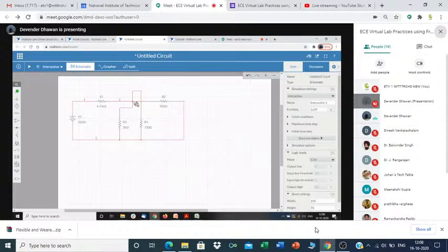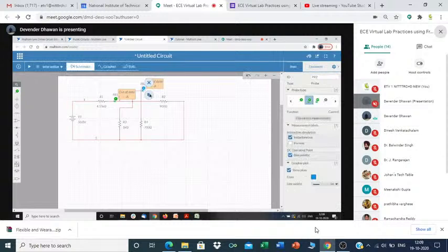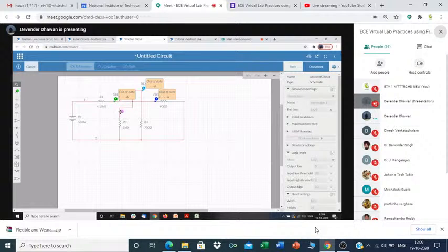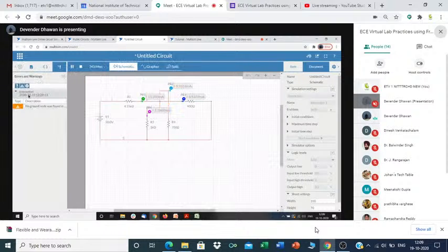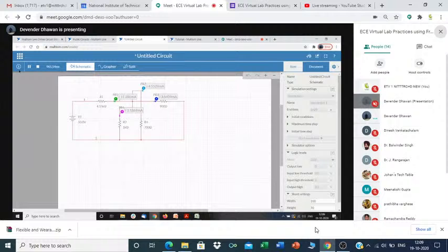On this junction, you can see that this is the input current line, and then this, this, and this would be the output. So whatever current is coming here would be equal to the sum of all these three. Let me just put some current probes, like here. We will see what current is coming here. Then one we will put here, and another we will put, let's say, here. Now we have current of all the values. Let me just run it. Oh, no ground is connected. So let me just stop and connect the ground here.